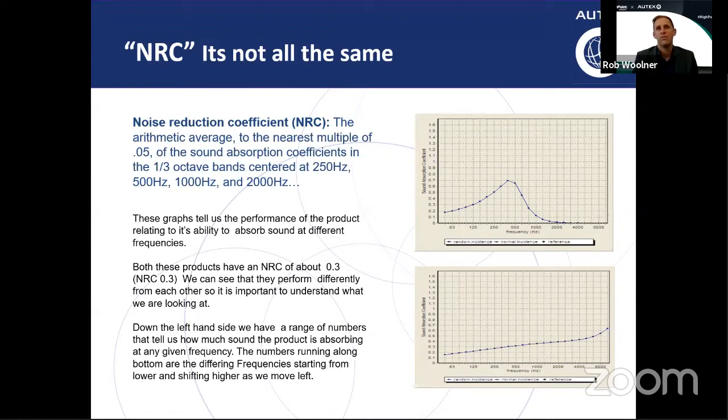You want to look at the low end frequencies traditionally to absorb the bass sounds. So that will be within music studios, media suites, those types of areas where you need that low end absorption. When you're talking about a classroom, typically you need to absorb at a higher end frequency, which is where the teacher's voice, female voices, children's voices are at that higher end.